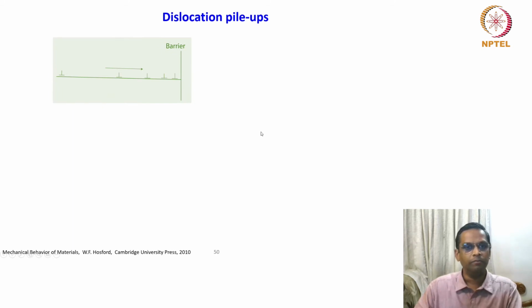So the next important aspect of this dislocation mechanics is dislocation pile-ups. Again, we will use this term quite frequently in the deformation behavior of polycrystalline materials as well as single crystalline materials. There is an obstacle for dislocation motion, and whatever dislocations get generated inside the crystal get piled up against this barrier. This kind of situation.